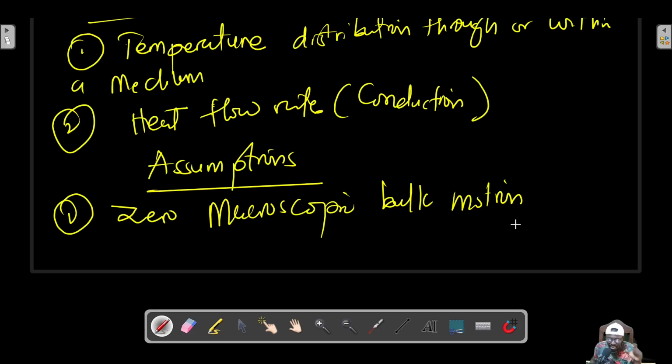Now, I said that convective heat transfer is conductive heat transfer plus advective heat transfer. Now, what is conductive heat transfer? You have a material, you subject one part of the material to heat. Now, what happens? The atoms over there are locked in their lattice. They don't have any net motion from their initial position, after they've gained the kinetic energy by absorbing the heat energy from the heat source, right?